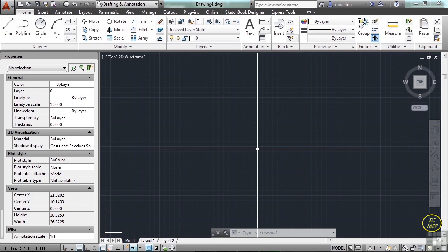And then now let's say, well, you know what? All those 36-inch doors, I want them to be 34-inch doors. You have to change them. So you have to delete them all, reinsert. That's some extra work. But if you had a block in there for that door that was already a dynamic block, then you could design it so that it would fit all of these needs, but with just one block. That would help you to make the changes very quickly. It also makes these blocks more useful since one block can fill many needs.